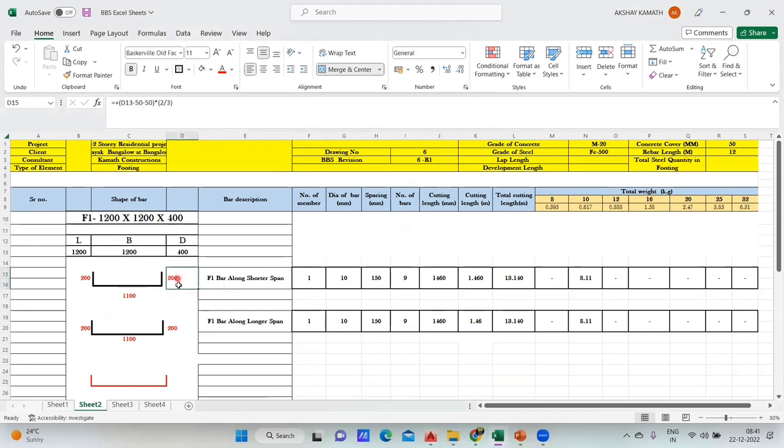Also this depth, whatever I've taken, that is 200 and 200, here we'll not put 2/3 and 2/3. That also we will do, because I'll teach you all the methods, and then it totally depends on you what you want to follow. Few people don't do 2/3 here. They directly take overall depth minus top cover and bottom cover. That will be the L. In that case, we need to take out this 2/3. But in most of the construction practices that we follow, we usually take 67% of that value. That is why I've written 2/3. If you don't want to do that, you strike out this 2/3 from there. Similarly, your answer is going to change. Okay, fine. We'll see you back in the next lecture. Thank you.